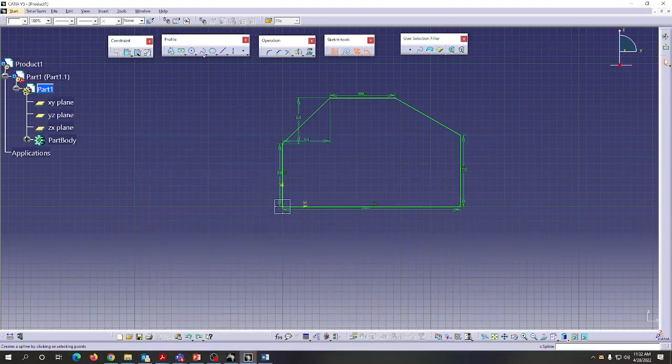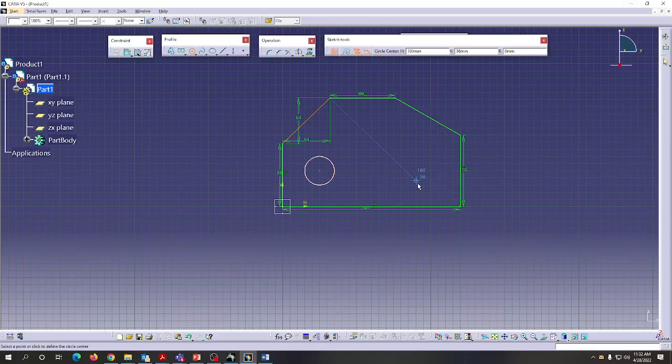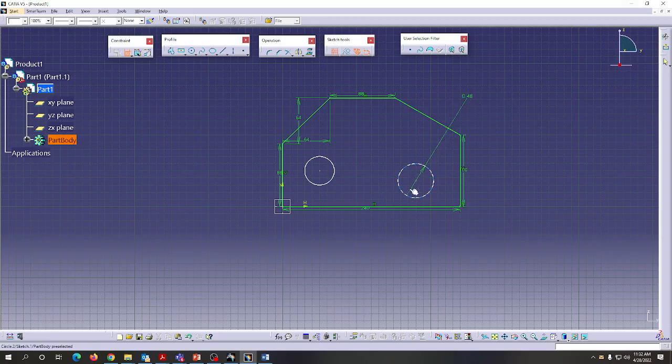Anywhere I will locate it. First I have to click the circle. I am just locating it here. One more circle, I need to click this icon again. I am just locating it here. So first constraint, we need to define the dimension for the particular circle. For that I am clicking it here. I am doing a double click. First this diameter, which is automatically generated, I am putting outside for clarity to see.